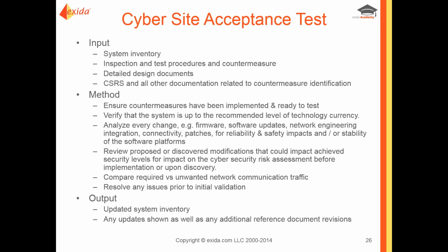Any proposed or discovered modifications that might impact the security level all have to be looked at before implementation, and preferably you'll do that upon discovery to be a little more efficient. Once again, now that you've got more complete communication traffic, you'll compare the required versus the unwanted network traffic. And lastly, resolve any issues prior to the formal initial validation.